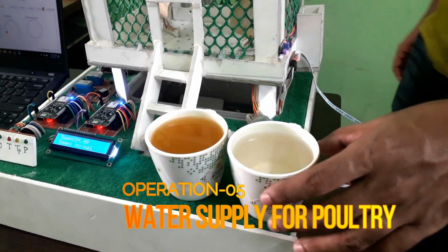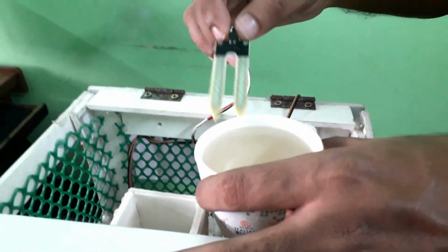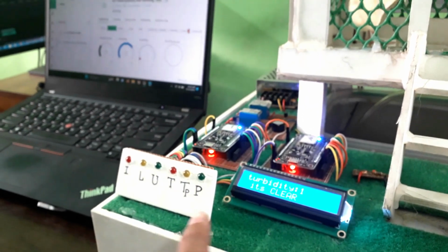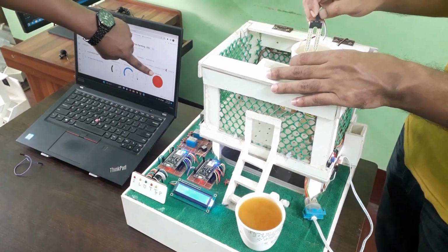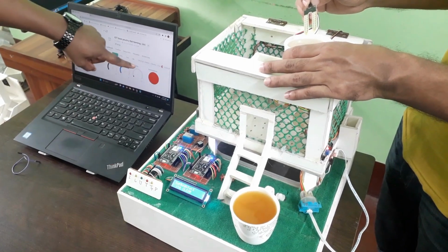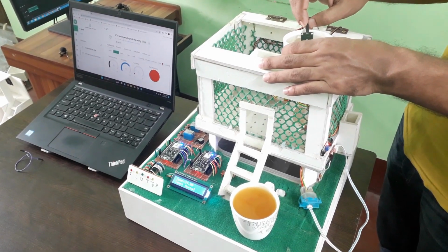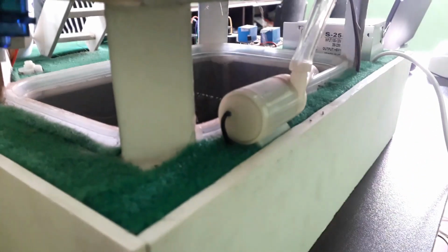Now we will check the water availability for the poultry farm, and for that we use a soil sensor. When this soil sensor gets a water connection, at that moment the water pump will be turned off, and the LED and Blynk app also show that. When this soil sensor is not connected with water, at that moment the water pump will make sure of water supply to our poultry farm from our pond. When the water pump is turned off, the LED will be turned off and Blynk also notifies about the water pump.